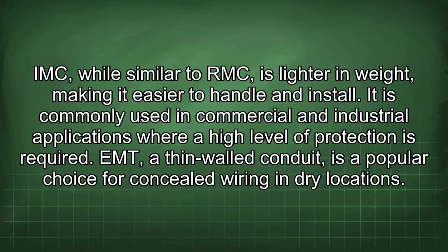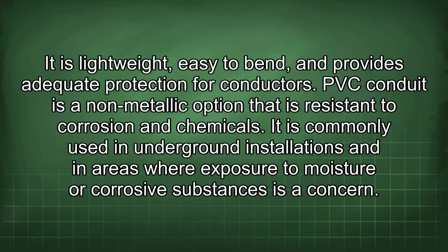IMC, while similar to RMC, is lighter in weight, making it easier to handle and install. It is commonly used in commercial and industrial applications where a high level of protection is required. EMT, a thin-walled conduit, is a popular choice for concealed wiring in dry locations. It is lightweight, easy to bend, and provides adequate protection for conductors.